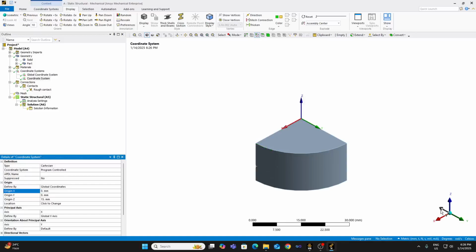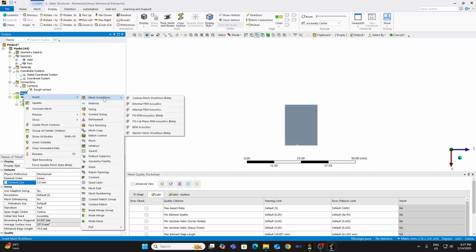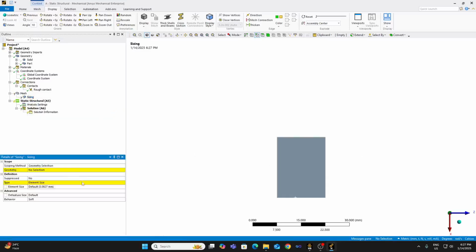Okay, and I'm going to use sphere of influence for the mesh control. So the global sizing is 2 millimeters. Actually, I'm just using one control, that is sphere of influence. Where is that? Yeah, sizing. Then select this particular face, sphere of influence, sphere center, the newly created coordinate system, sphere radius. I'm taking just the radius of the indenter. Should that suffice?